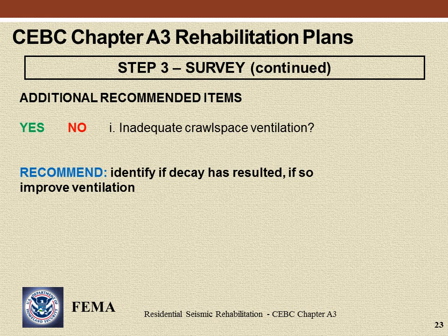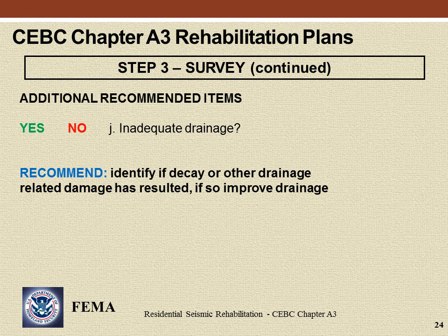Inadequate ventilation should be identified. Where inadequate ventilation has led to wood decay, it is recommended that ventilation be improved as part of the seismic rehabilitation work. Inadequate site drainage should also be identified. Where inadequate drainage has led to wood decay, it is recommended that drainage be improved.